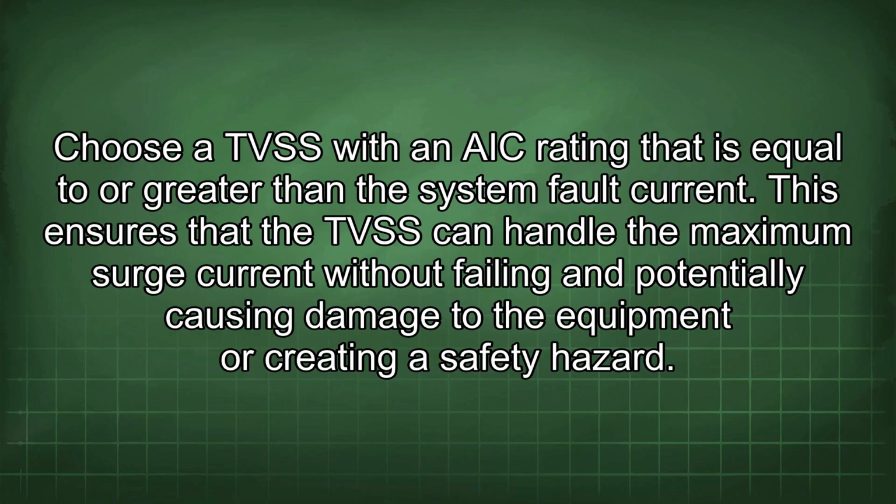Secondly, select the TVSS AIC rating. Choose a TVSS with an AIC rating that is equal to or greater than the system fault current. This ensures that the TVSS can handle the maximum surge current without failing and potentially causing damage to the equipment or creating a safety hazard.